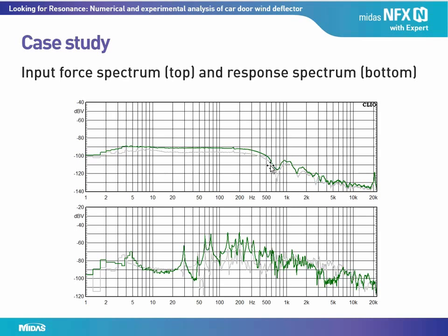In some strikes, multiple hitting occurs. In that case, a comb filtering effect would be seen in the force spectrum. You will not see a flat region here, but a comb filtering-like spectrum going up and down all over the measured bandwidth. The bottom graph is the response spectrum. Resonant peaks are seen clearly.